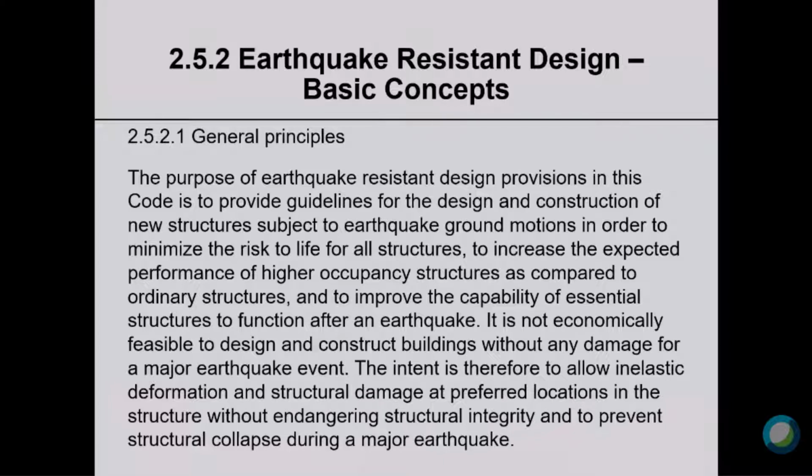Subject to earthquake ground motion, then in order to minimize the risk to life for all structures, this is one of the purposes or aims: to minimize the risk to life, to increase the expected performance of higher occupancy structures as compared to ordinary structures. Higher occupancy structures would be where a lot of people congregate in one space in one place at one time.